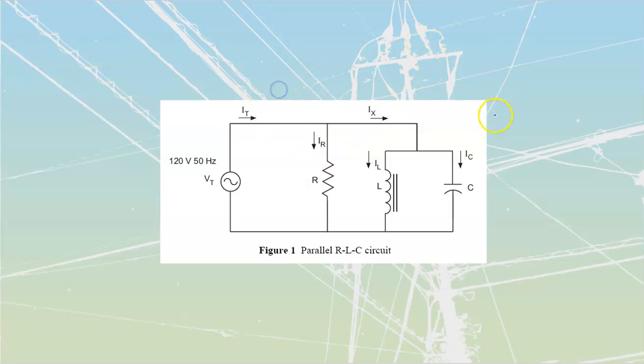And this type of circuit setup, a parallel circuit, is going to be a really common type of circuit setup for us to have. We know that that's what we connect almost every circuit out there as. Because we use this parallel circuit in so many places, we should be familiar with what our voltage values are going to be. We know for a parallel circuit, the voltage of my source is going to equal whatever I've got across my resistor, which equals whatever voltage I have across my inductor, which equals whatever voltage I have across my capacitor.